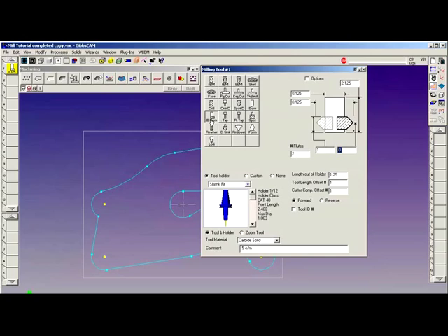A back boring bar, overall length, shank diameter, cut diameter, number of flutes, and in this case, we have the touch off distance from the bottom of the bar to the top of the cut, which is typically used when doing back counter boring. You want to be accurate in the depth of your counter bore, so we need to specify where the cut is being taken. In the back counter bore, it would be the top of the back boring bar. And as I mentioned, number of flutes, and the same as the regular boring bar, touch off to the cutting edge. That value would go in this dialog here.